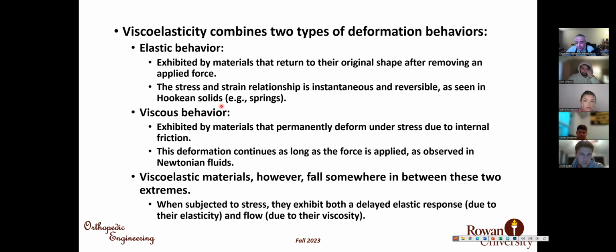Viscoelastic material is between these two. It is not purely elastic. When you apply the stress, it cannot undergo full elastic deformation because the viscous part does not allow rapid changes. And when it is under constant stress, it is not like pure viscous material that undergoes constant deformation, because the elastic part prevents this constant deformation in the viscous phase. So you have something between full elastic and full viscous behavior.